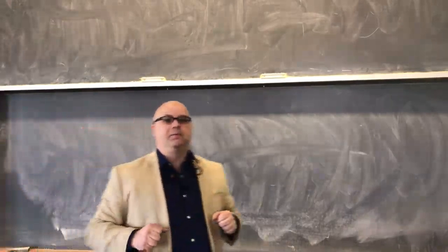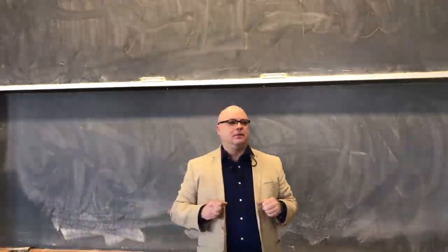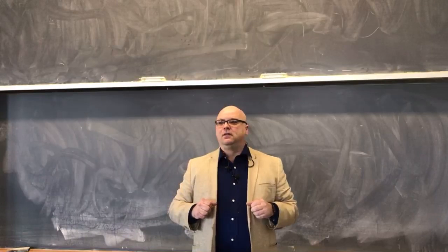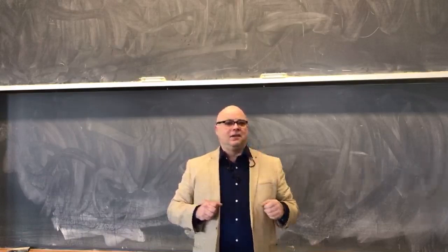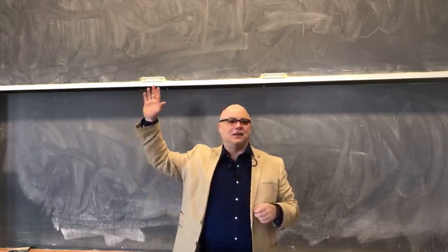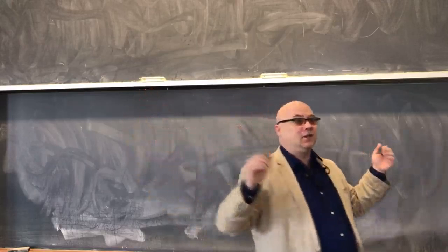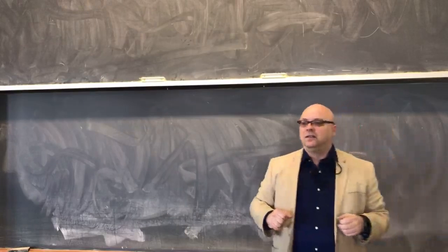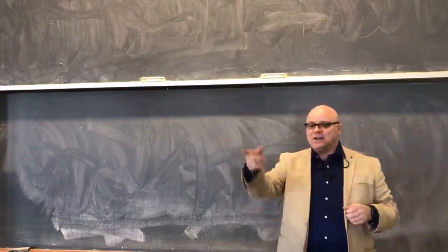So what's a thou? It's Technobabble for machining, right? A thousandth of an inch. What's a tenth? Anybody? You might think so. Who thinks a tenth is a tenth of an inch? A thou is a thousandth of an inch. Raise your hand if the first thing that comes to mind is a tenth of an inch.